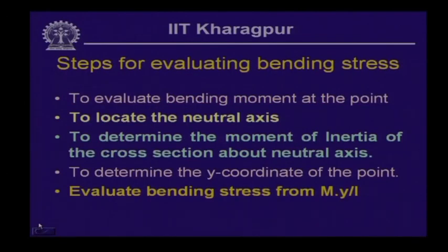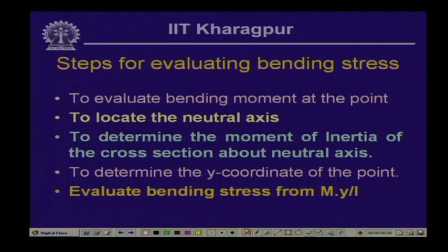Well, these are the steps, as you can visualize now, that we should go through if we are interested in finding the bending stress at a point in a given cross section, so that we can evaluate the stress. As you can appreciate, at the section where we want to find the stress, we must know the value of the bending moment it is subjected to because of the external load acting on the beam.